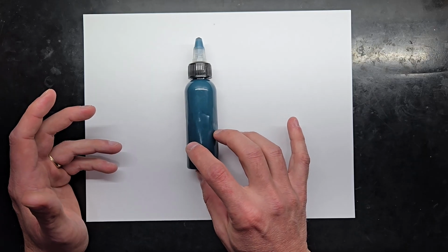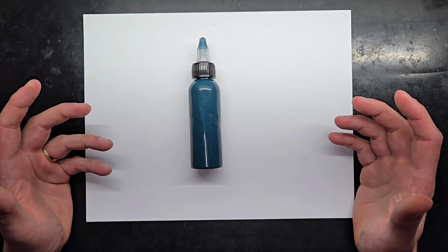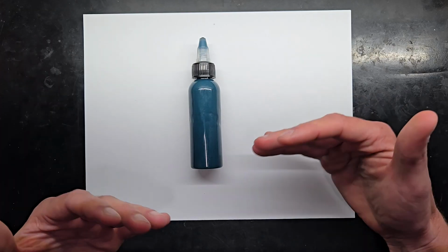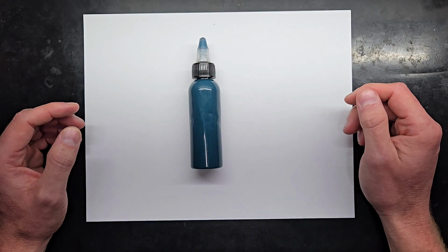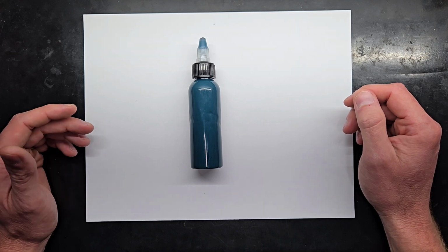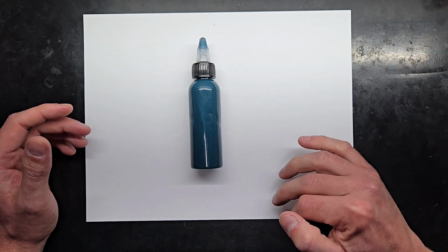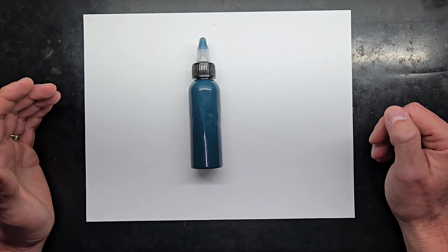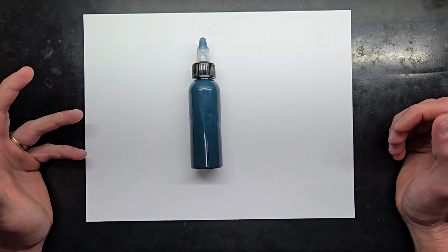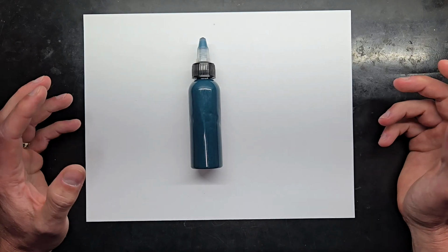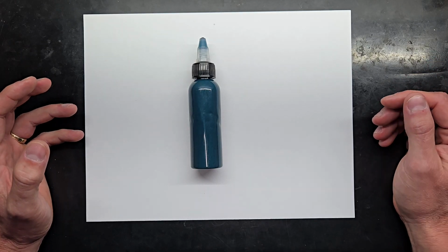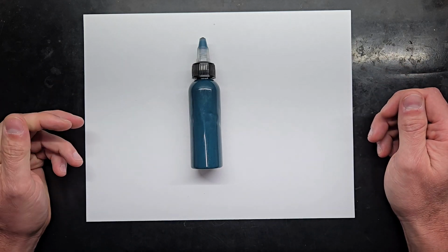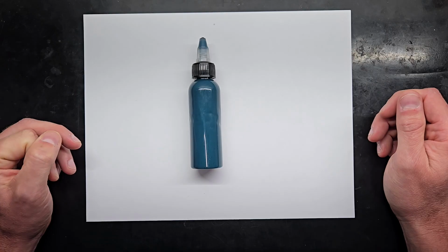And so there is a rheology tester where they can heat and cool the grease, and they can shear it at different rates, and they can do a lot of testing to develop curves to understand how the grease behaves, how it reacts, and how it rebounds. And with that level of understanding, you can really tune greases to get pretty exacting performance out of them.